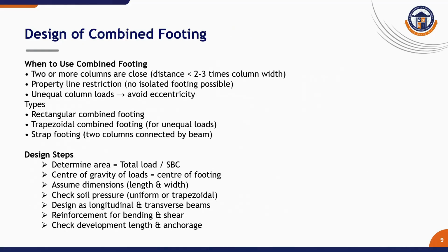Treated as a cantilever for landing on the continuous slab, provide main reinforcement along the span, both bottom and top, provide distribution steel perpendicular to main bars, and check for shear and deflection. Steps are considered as rectangular load and triangular load on the waist slab, and are to be designed separately.